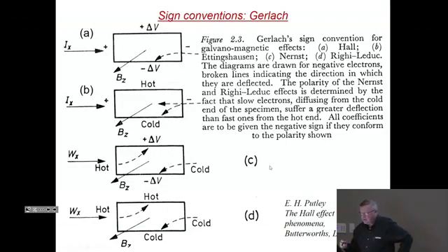Okay, so let's go over what we do for the Hall effect, right? Hall effect, you pass an electric current this way, and you pass a magnetic field out of the plane of the blackboard here, and you put the positive electrode on this side and the negative electrode on this side, and then your Hall effect will be positive when your carrier is a hole. Basically, you calculate the Lorentz force on a hole that moves at the velocity in this direction, and you will see that your field will deviate it so as to have your red wire become positive and your black wire become negative.